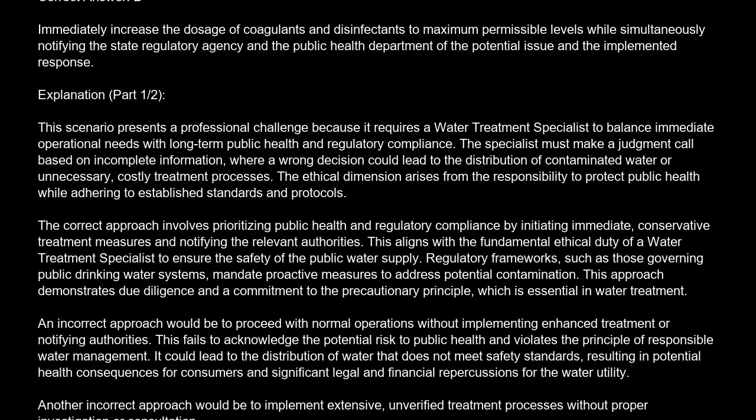The correct answer is B. Immediately increase the dosage of coagulants and disinfectants to maximum permissible levels, while simultaneously notifying the state regulatory agency and the public health department of the potential issue and the implemented response.